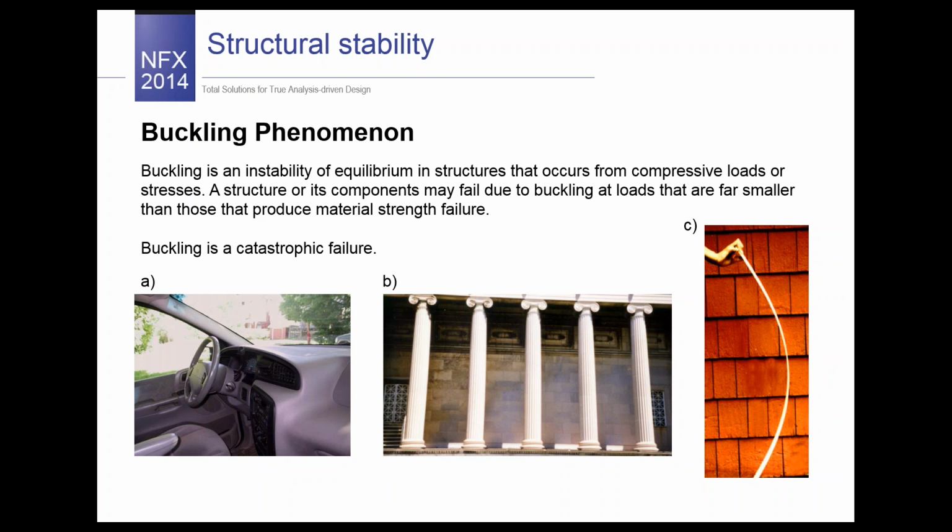And buckling is commonly understood as instability of columns under compression, and any axial members that support compressive axial loads are called columns, but not all structural members behave the same. If a compressive axial force is applied, for example, to a long strip, then it bends significantly. We can observe this response in picture C. If the columns of a building were to bend in the same way, the building itself would collapse. And when a column buckles, the collapse is usually sudden and catastrophic.